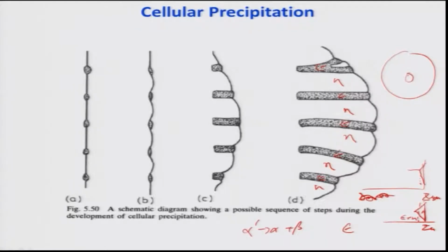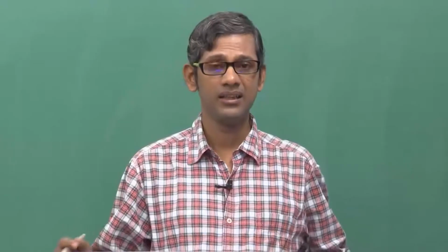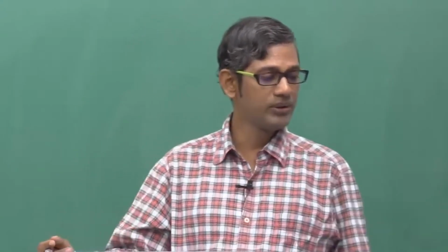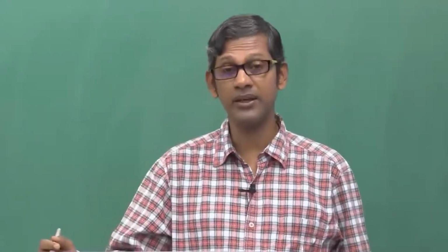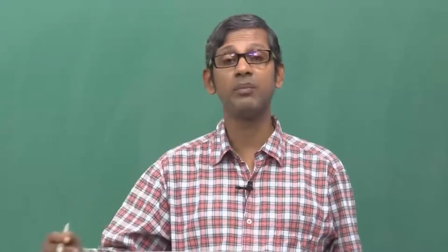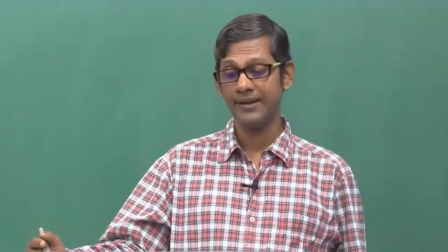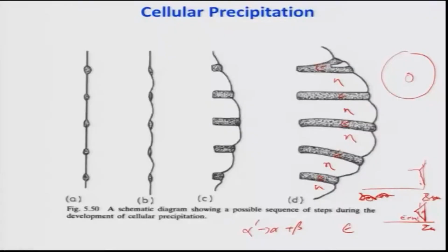So in order to create such a large interface we need energy. That is why the bulk part of the free energy available to the system is basically used to create these interfaces. What is the advantage of lamellar morphology? As you have seen in pearlite, it reduces the diffusion distances. In fact, for these kinds of precipitates to grow, it is basically lattice diffusion which happens.